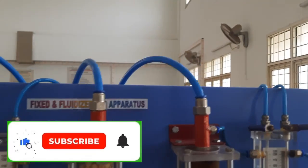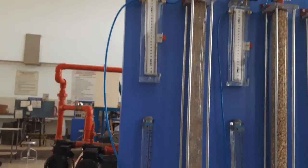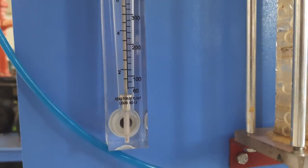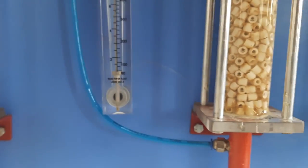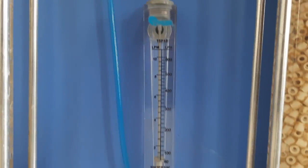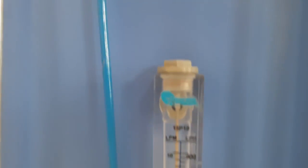And if you look at the new experimental setup, the fixed and fluidized bed setup, in which we have 3 different particle sizes, for each packed bed we have a rotameter attached to it. You can see that it is a transparent glass with a float in between, and there is a tapering section with a varying diameter. From bottom to top there is a calibrated scale.